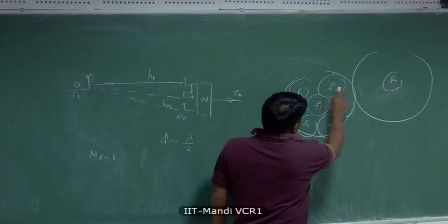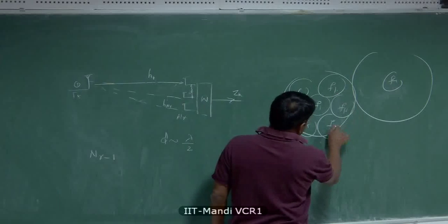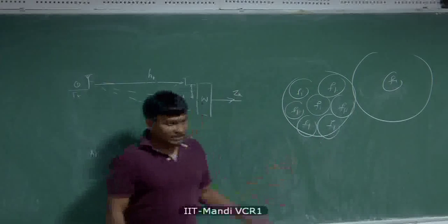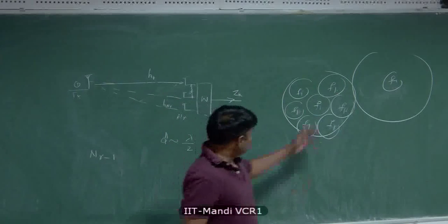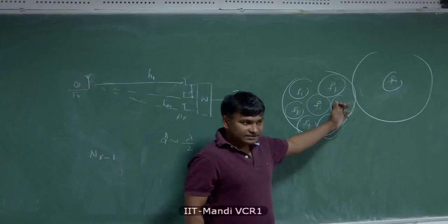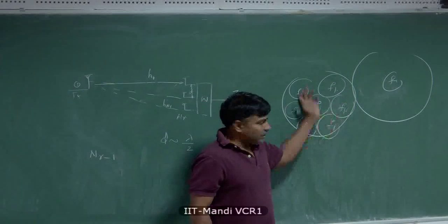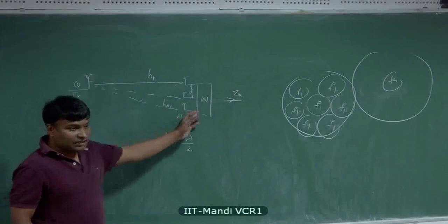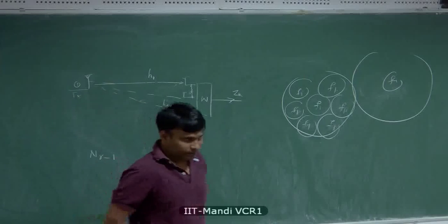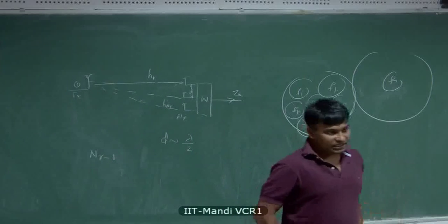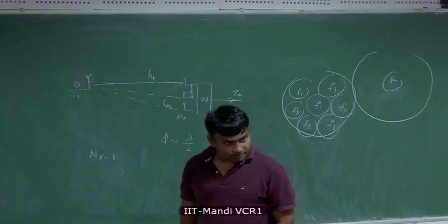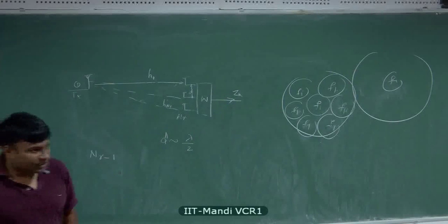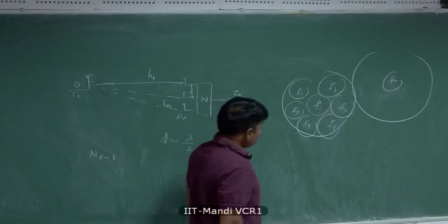But on the other hand, if you reuse all the frequencies in all the cells, then you can increase the capacity in a significant way, because in the previous framework you need a lot more bandwidth. Now you can reuse them very aggressively in all the cell sites and use a technique of this kind to reject co-channel interference. So the overall spectrum utilization will increase. That's one benefit that you could possibly get from this.